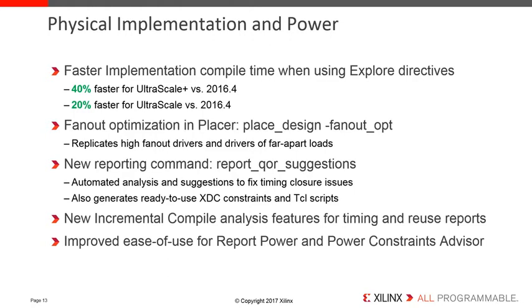In the area of physical implementation, there are quite a few new features targeted at decreasing runtime and improving quality of results. We are seeing improvement in compilation times of up to 40% for UltraScale+ devices and up to 20% for UltraScale devices versus 2016.4 when using Explorer-based strategies and directives.